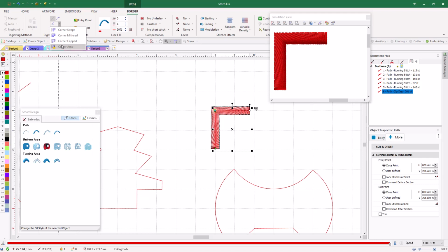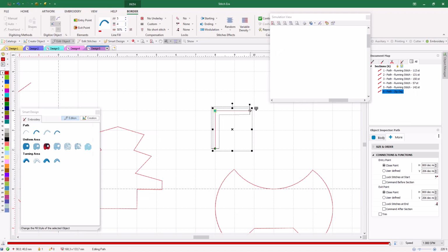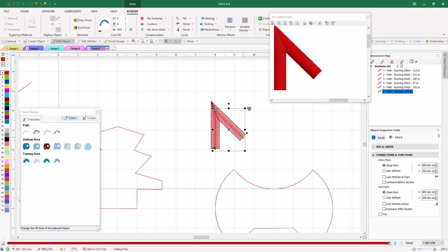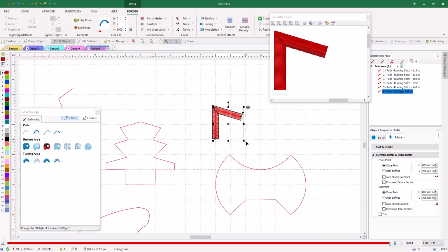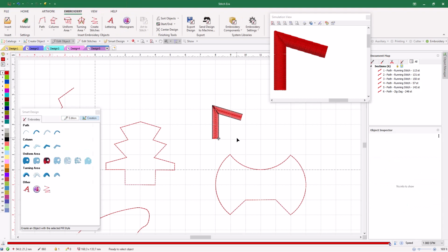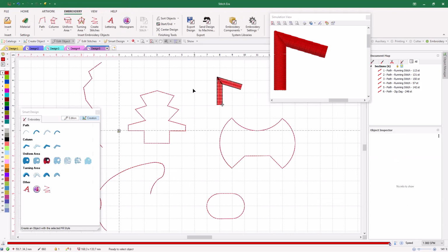When a corner node is automatic, the system selects the corner model according to the angle. To maintain a uniform style in the corners of an object, we can force the corner nodes to one of the models, opening the options in the Tool tab button. Probably the most versatile model is mitred. If we create paths with curved corner nodes, the behavior is the same. Well, this is all we need to know about nodes, so, let's open an image and create some objects manually.